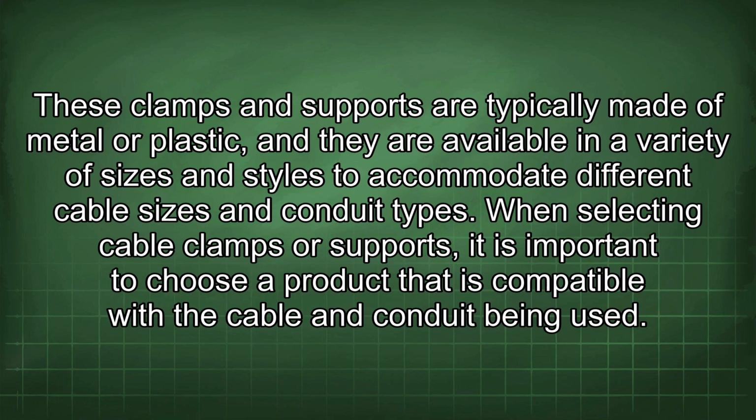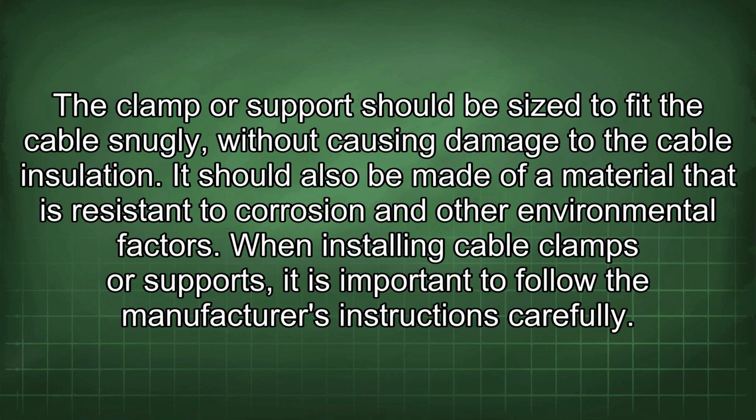When selecting cable clamps or supports, it is important to choose a product that is compatible with the cable and conduit being used. The clamp or support should be sized to fit the cable snugly, without causing damage to the cable insulation. It should also be made of a material that is resistant to corrosion and other environmental factors.